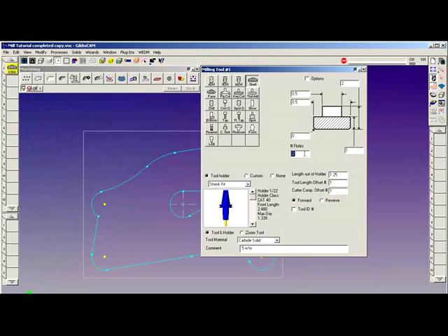This may be a 6 insert shell mill with the height maybe here 0.625. This would ensure that when you rendered the part, you would see when you've surpassed the depth of cut, and it would show up in red in the rendering. Face mill, defined the same way. And so is a fly cutter. Fly cutter may be a single flute fly cutter.